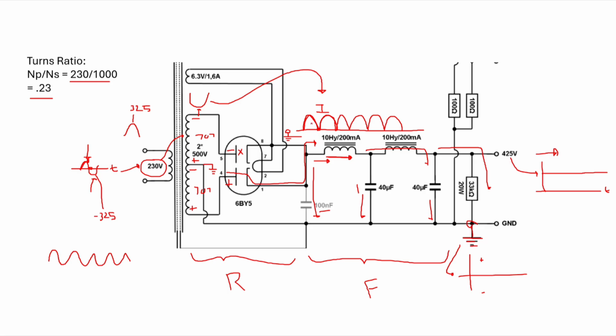So this will be a low pass filter, and it's going to tend to smooth these humps a little bit, like that. So when we pass this inductor, we're going to get what's called ripple. We're going to get a smoothing effect right there. This capacitor also, when a capacitor is in parallel like this, it's the same thing. It's also a low pass filter.